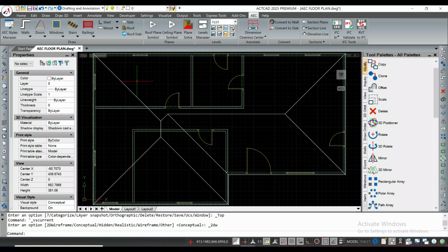I'll be using the two largest icons first and later discuss the others in more detail. The section line and elevation line icons look like they'd insert the annotation block shown, but they don't. They create a view plane that has a default depth. I'll start with the elevation line to demonstrate.